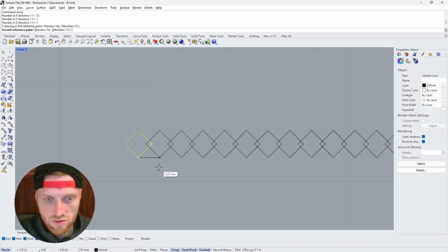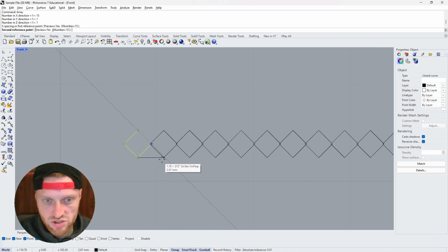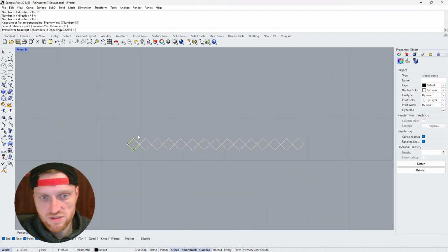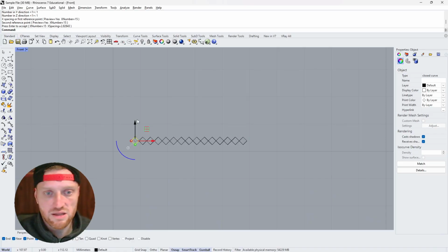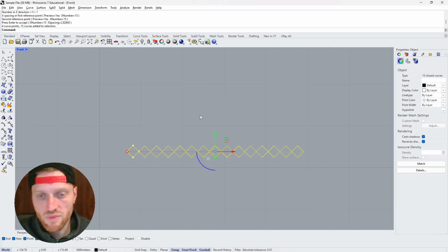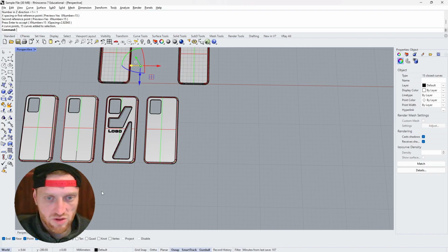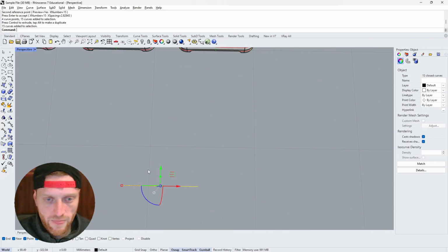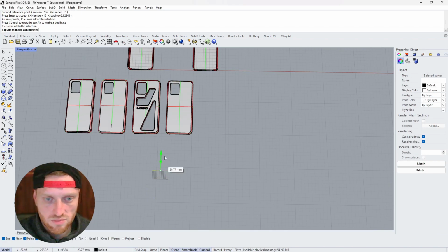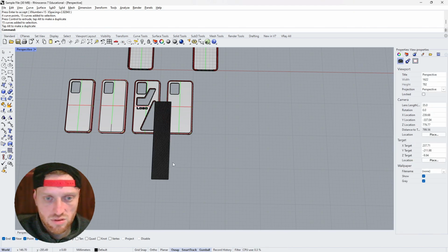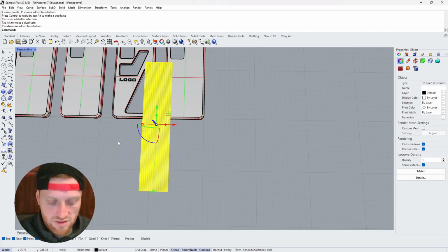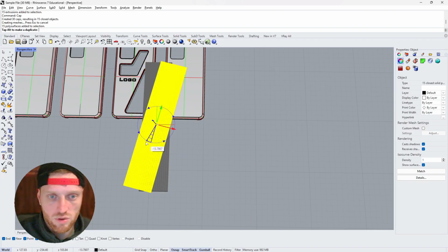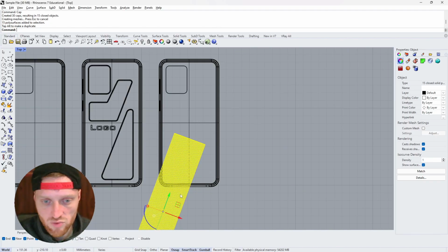And now I click on the first base point as my reference in terms of dimensioning. And I want them to connect at one point. So this is what we get. So now I have exactly 15 copies of the square. What I can do next is I can move it where I want to. And now I will just extrude them really long. From the right, I select them and cap. Now I have solids.